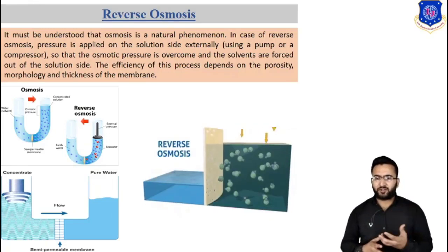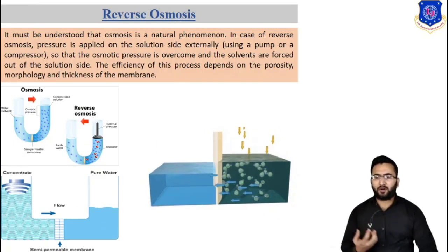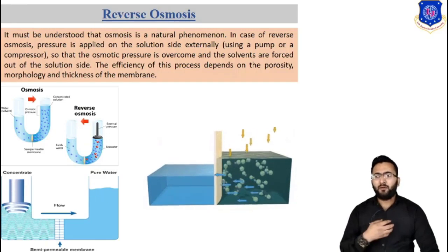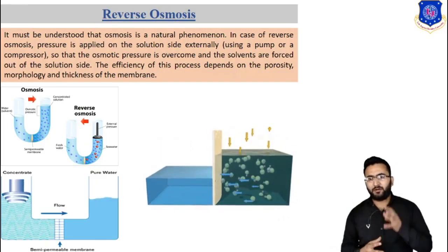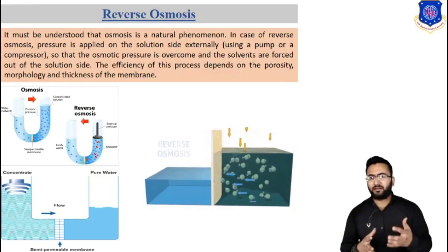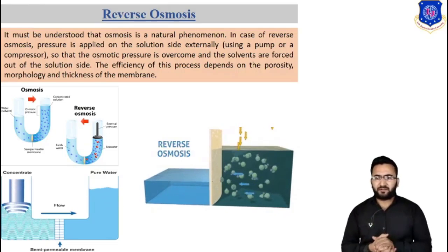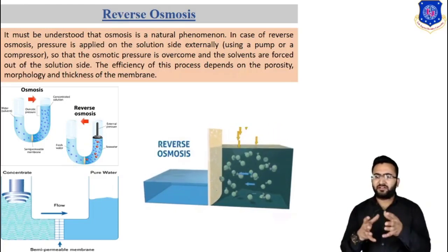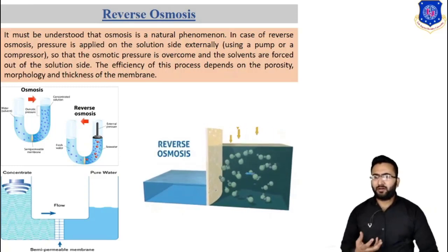Since reverse osmosis membranes have a very small pore size, they are used for the separation of lower molecular weight species such as salt. Salt has a very low osmotic pressure. The operating pressure on the feed side of a reverse osmosis process is therefore extremely high. This will lead to the deposition of salt near the membrane surface, leading to build up of a concentration boundary layer. Therefore, the pressure gradient in this system leads to a concentration difference. So this is all about reverse osmosis.